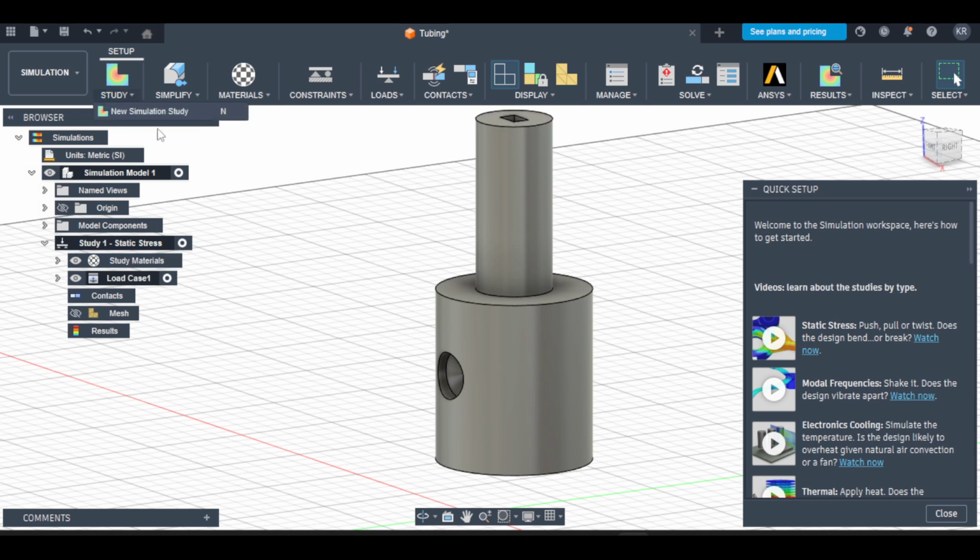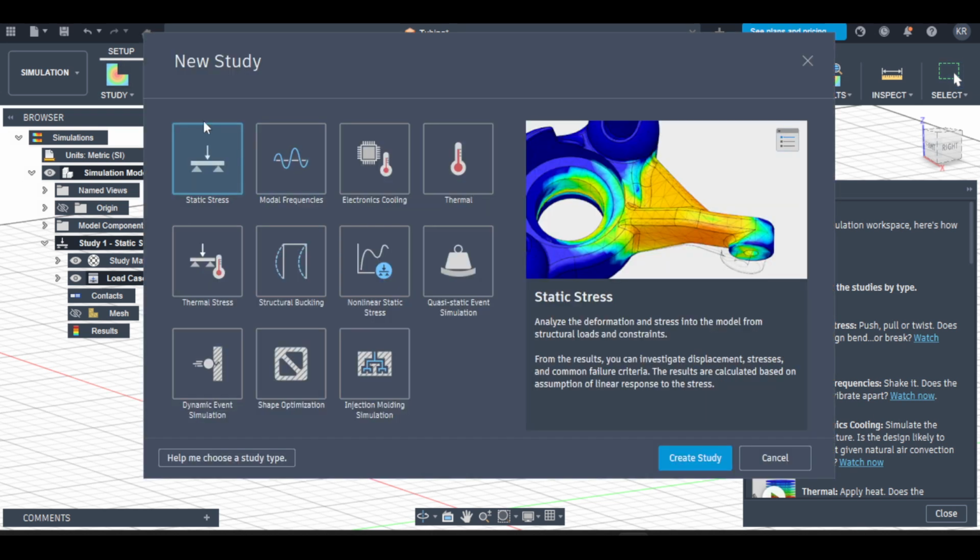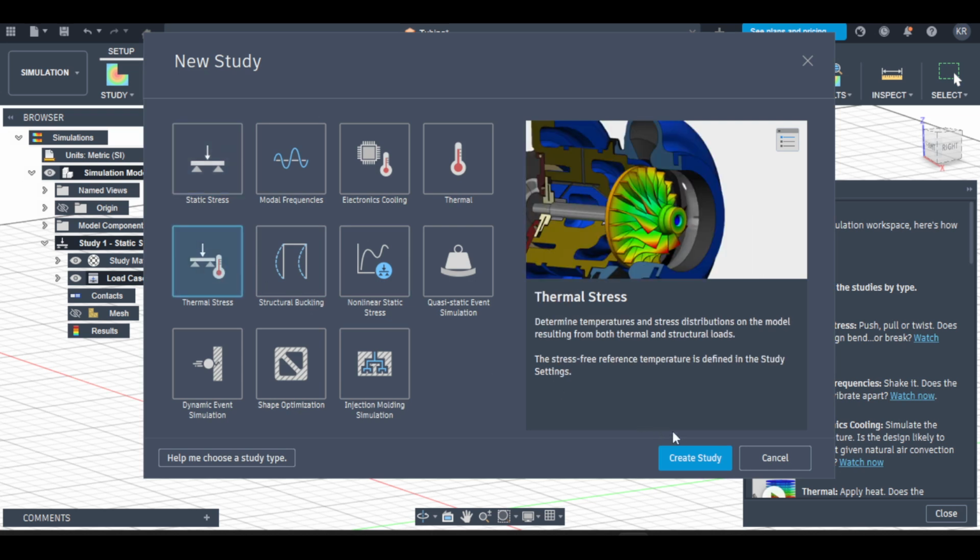Assign materials to all components. Accurate materials are essential because stiffness, strength, and mass come directly from them. Open the material assignment panel and apply the correct material to every part in the model, not just the main body. Double check units and properties. Steel, aluminum, and plastics behave very differently. If you leave a component as an unspecified default, your results can be misleading.